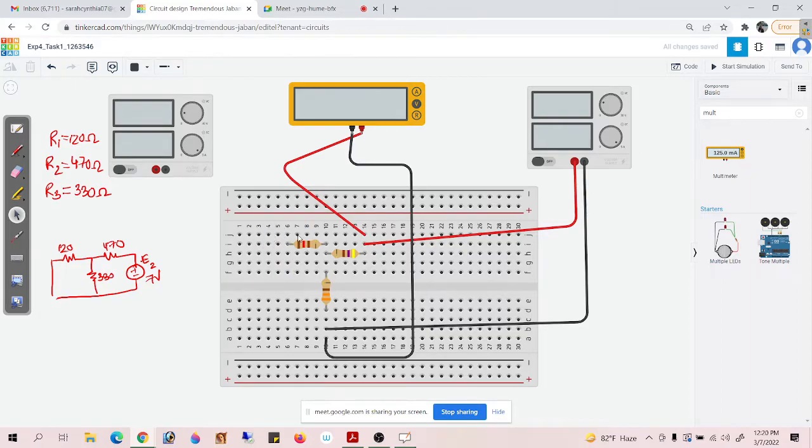The resistor here, R1 resistor, is basically open. It is not connected to any other component in the circuit, right? So what can we do? What does the circuit tell us? The resistance R1, if I short the voltage source, or if I deactivate the voltage source, the resistor R1 will be directly connected to the ground, right? So we will be drawing a wire from the resistor R1 and connect it to the ground. Did we all get it?